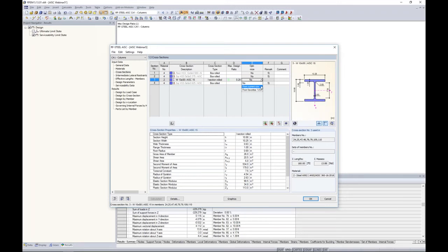You can optimize from the current row, meaning the program is going to choose any W shape from the AISC section. The other option is to choose one of your favorites list. Remember way back when we first drew this column, I had my favorites list USA with about, I don't know, 7 W10 shapes. So with this favorites USA now, if I want to optimize from just those 10 or so shapes, those W10s, then I can choose this option.